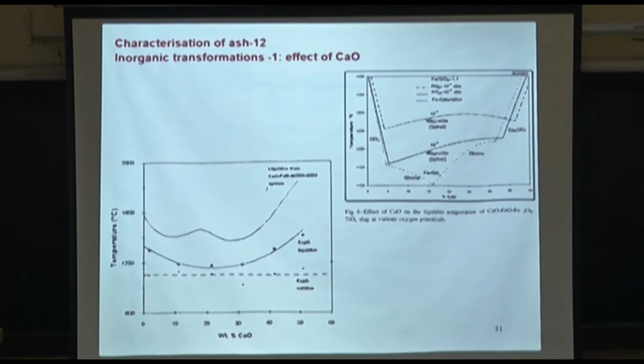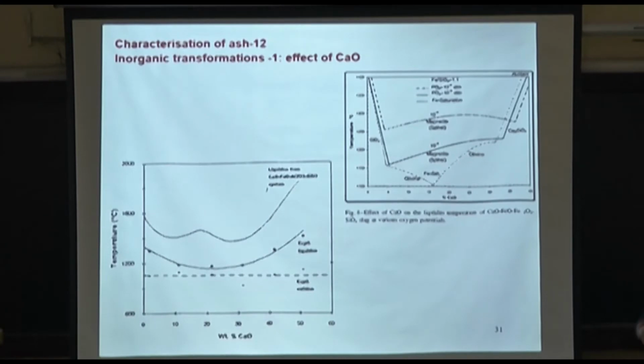Yeah, so what you do is you first do the EDX, get the elemental compositions, put that in the software, and then ask the software to calculate the proportion of every possible compound. Even though you wouldn't specify olivine or martensite or whatever, it will do it, based on the equilibrium constant values that it has inside its database, and it will actually draw precisely this. So you can ask it to draw it. It's all equilibrium calculations.